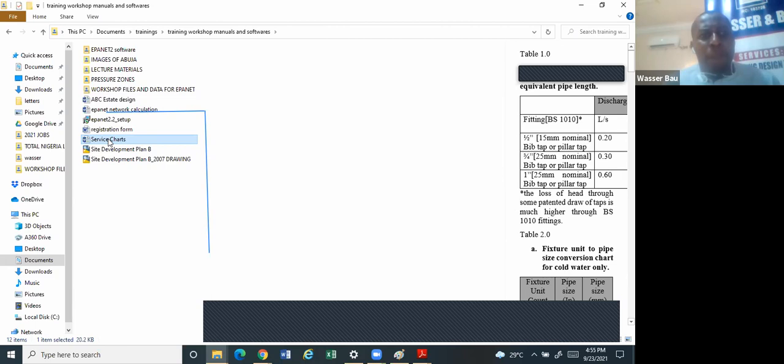but that does not mean that water will not flow. But for water to flow at a very effective, efficient, and standard flow rate, we expect the water pressure to be about 2 to 2.5, but 2 is the minimum. And the maximum, as we have said, is 8. And optimally, it should be between 2 and 3 in your network.